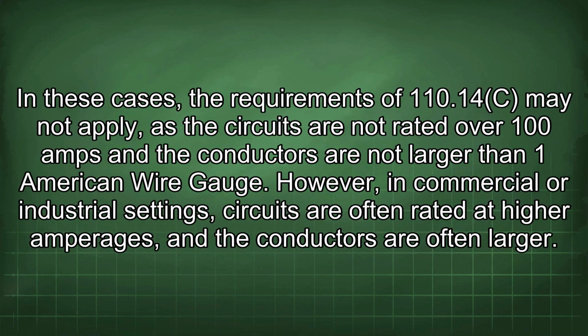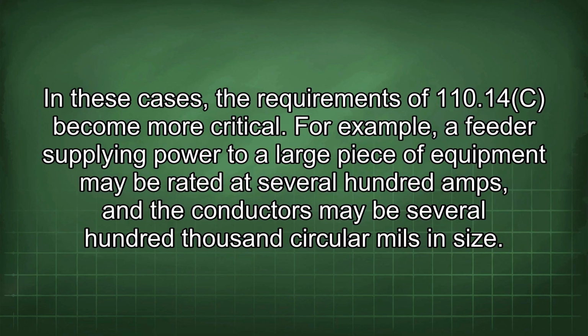In these cases, the requirements of 110.14(C) may not apply, as the circuits are not rated over 100 amps and the conductors are not larger than 1 American wire gauge. However, in commercial or industrial settings, circuits are often rated at higher amperages and the conductors are often larger. In these cases, the requirements of 110.14(C) become more critical.